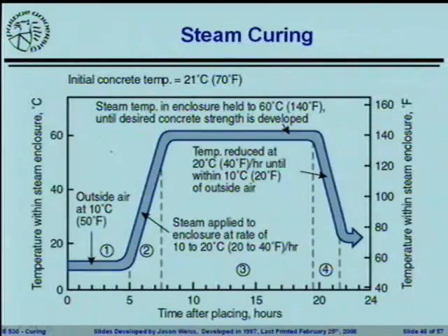Other aspects of this that you might want to look at, there are places where we will steam the concrete. Here you're looking primarily at precast applications. The name of the game, if you are making precast concrete elements, is to try to get the concrete in and out of the forms quickly so you can make some additional concrete elements. So one of the things that they will do is pump steam under a tent or steam through pipes in toward this concrete to try to raise the ambient temperature to make the concrete react faster.